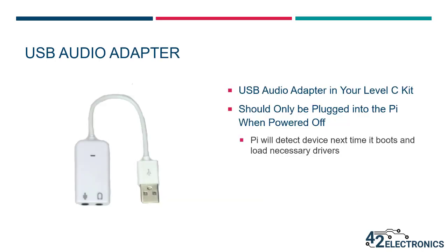The USB audio adapter included in your kit uses the General Plus chipset and driver. While this device is not called out specifically in the list of supported devices, this audio adapter adheres to USB audio standards, so it falls under the class-compliant USB sound cards at the bottom of the list. Using a device that conforms to USB audio standards will ensure the best possible driver and software support, as support for this type of audio device is built directly into the Raspberry Pi operating system and other Linux distributions.